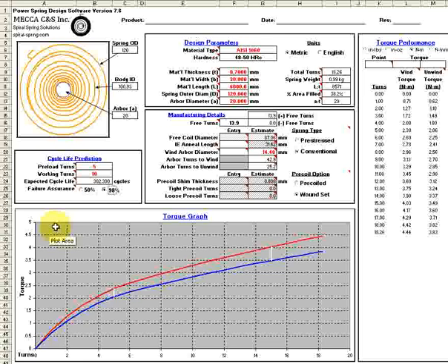Make note of the shape of the spring shown in the simulation. The visible dead turns tell a lot about the spring design efficiency. Too many dead turns are a sign of a high cycle life spring with gradually increasing torques. Very few dead turns are common to a spring that has lower cycles and a quickly increasing torque. Experience allows the user to adjust the design so that the dead turns match the design goals.